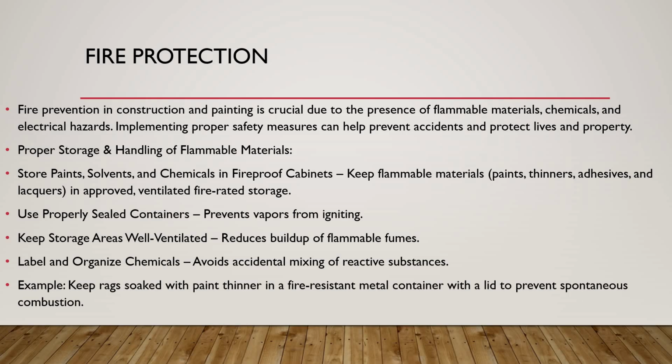Use properly sealed containers to prevent vapors from igniting. Keep storage areas well ventilated. Reduce buildup of flammable fumes. Label and organize chemicals. Avoid accidental mixing of reactive substances.